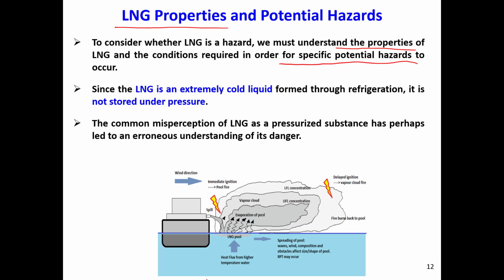As I know, many people think those LNG tanks are under very high pressure. That is not true actually. Why? Because LNG is an extremely cold liquid, at minus 160, 170 degrees. It's a liquid, first of all, not vapor. It's an extremely cold liquid formed through refrigeration and is not stored under high pressure.